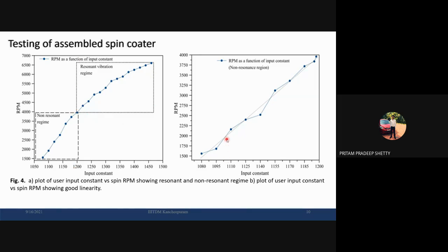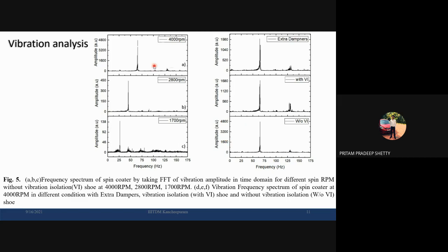What we thought was incorporating extra sponge all over the strategic places, such that you can further reduce the vibration. Here I placed an accelerometer at different positions on the device and recorded the amplitude for a specific amount of time. If you apply a Fourier transform to that signal, you will get certain peaks. These peaks correspond to certain frequencies of amplitude which is repeated. This frequency will give you the cyclic vibration which you will observe in your device.